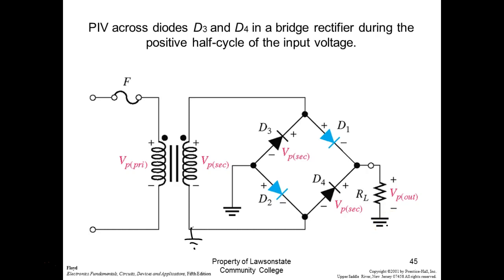Now I could do what? I could disconnect my other ground and go across the transformer. Right? Y'all understand? Because what I've just done is I've shorted out that diode right there. I put the same connector on both sides, right? You understand that? Because what you have to understand, this is a piece of wire. Now I'm getting that ground through my oscilloscope, but if I was to come over and click that, what I've done is I've connected a piece of wire right there, right? Y'all understand that? So now I got a short circuit. I burn up my diodes or mess up my transformer.